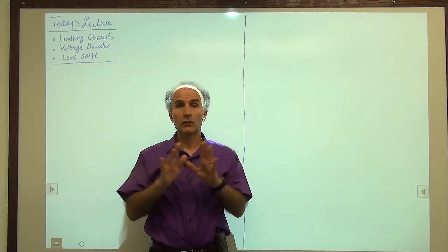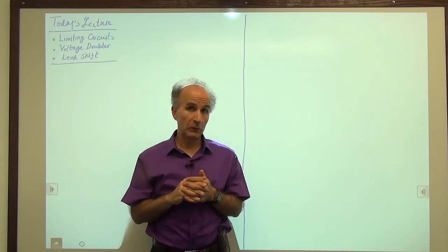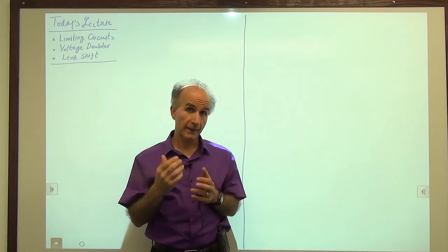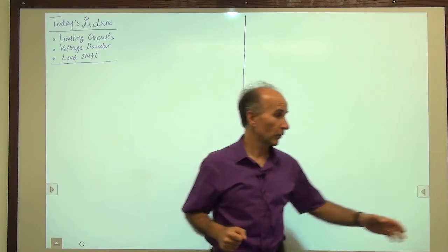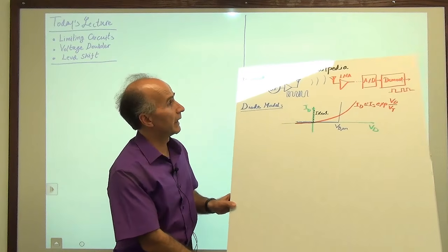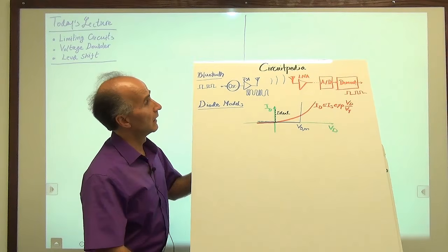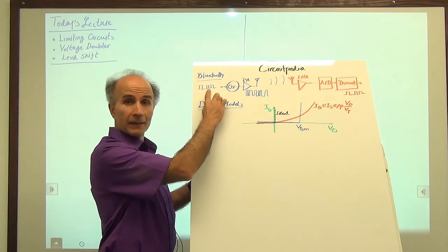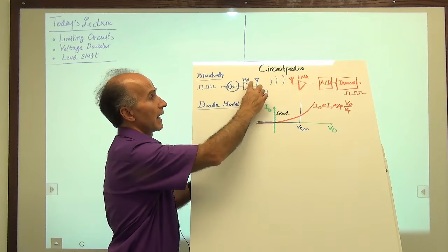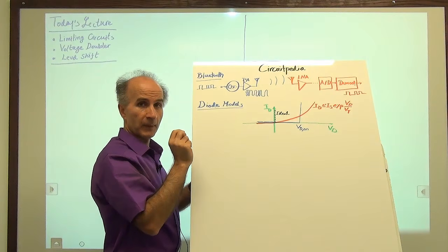Well, to give you the context, remember when we talked about the Bluetooth system, we said that the transmitter sends out a waveform according to the data that we have. So here's our Circuitpedia, and you can see that the Bluetooth system takes the data, applies it to an oscillator, modulates the frequency, and then goes through a power amplifier and transmits the data.